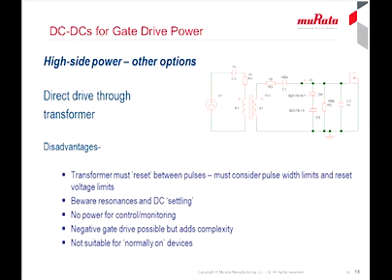All transformers like this have to have a zero net magnetization after each switching cycle, otherwise they would quickly saturate. This means that the transformer has to be allowed to reset with the same volt seconds on positive and negative waveforms. The reset voltage therefore varies with duty cycle, and to control it adds complication.